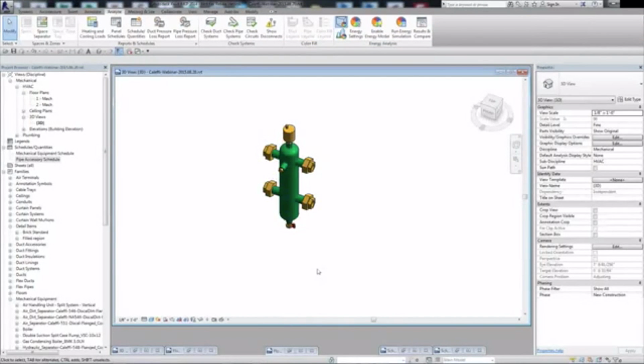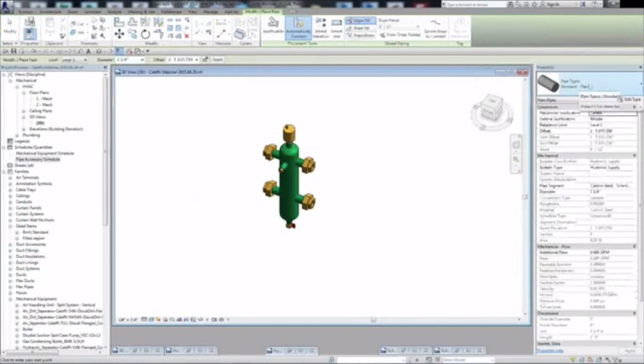So Revit doesn't actually know the components that you're using and whether or not you're using plastic pipe versus metal pipe. Again, it's not dummy proof. You still need to know what types of pipe you're connecting to which systems. Certain systems are defined under the piping systems, in this case there's only 3, but the pipe types are usually defined as hydronic supply, domestic hot water, domestic cold water, sanitary, what have you. And then you apply whether the pipe is plastic or metal or PEX within the properties for the pipe types. That could be built into the library, like if a PP type of pipe is coming out, that manufacturer could have you build the BIM files. That pipe would be in there then. That's correct. Yeah.